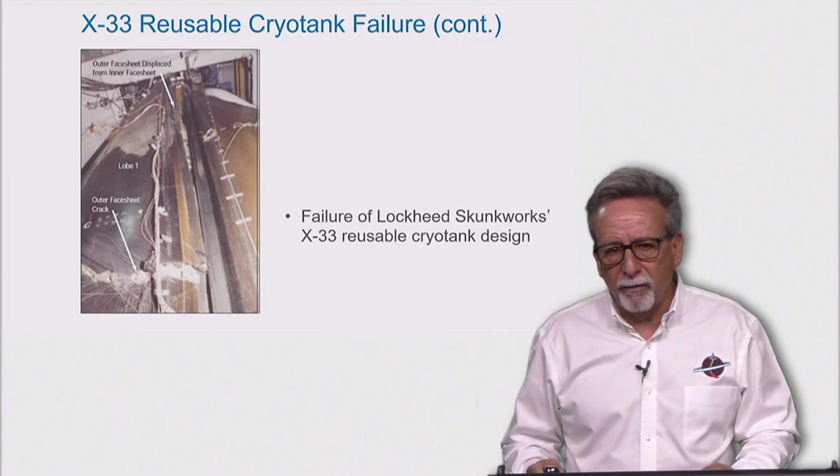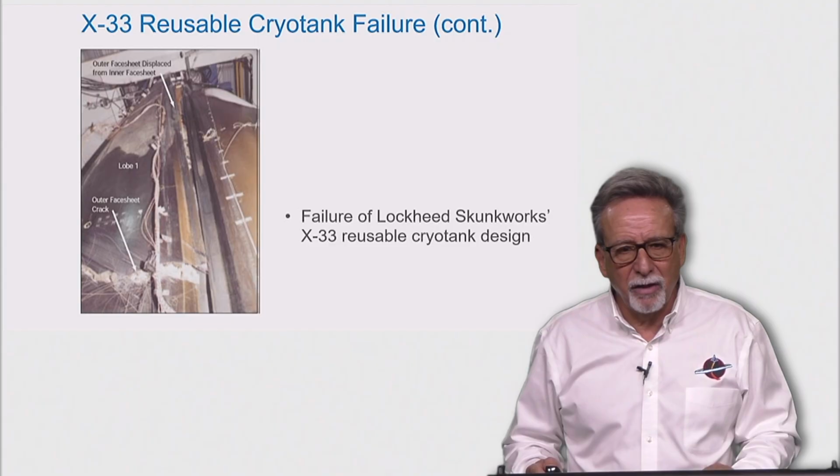Once the tank is drained during the test procedure or during boil-off during launch, the liquid level in the tank drops sufficiently, the trapped liquid hydrogen or liquid nitrogen vaporized, pressure within the cells rose, and the honeycomb skin blew apart, as shown here. As Henry Petrosky warns, neglecting details, not recognizing all the potential failure modes, and not designing to obviate failure caused this design to fail.